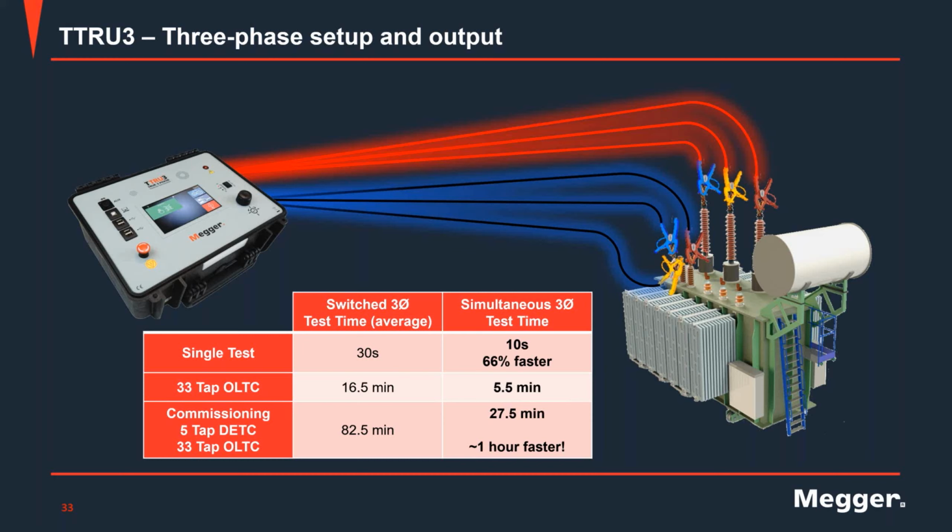And remember, it's not only that you're getting the results faster, but you're also getting better accuracy, because you're energizing simultaneously the three phases of the unit, and you can also perform the measurement using the step-up technique.